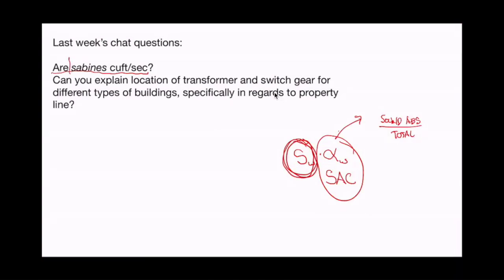And so the reason you can think of Sabins as square feet: if you have a room with 750 Sabins, then that means, in terms of how long sound lingers, it's as if you had a theoretically completely sound reflective room with no absorption, and then you had 750 square feet of opening, of just window where the sound just leaves.